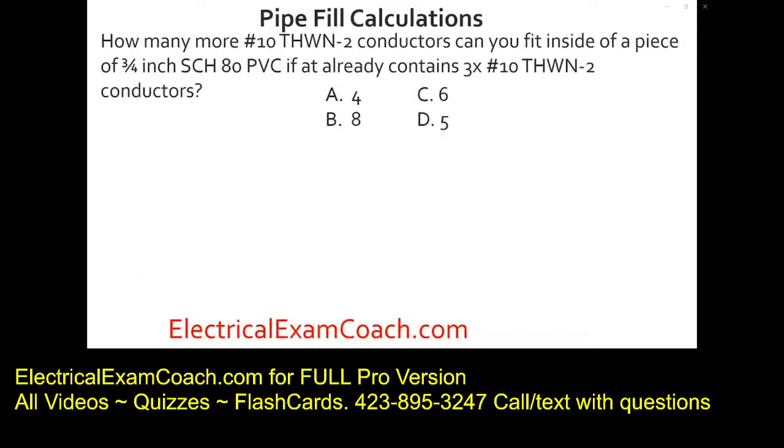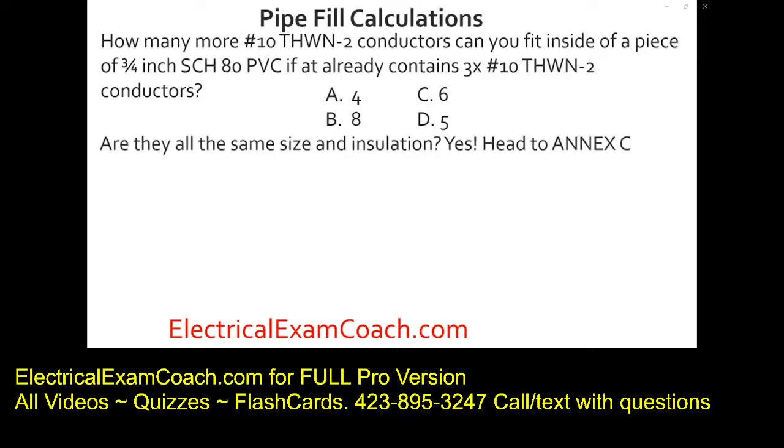How many more number 10 THWN-2 conductors can you fit inside of a piece of 3/4 inch Schedule 80 PVC that already contains 3 number 10 THWN-2 conductors? The first question we're going to ask ourselves: are they all of the same size and insulation type? They are. So we're going to head straight to Annex C.